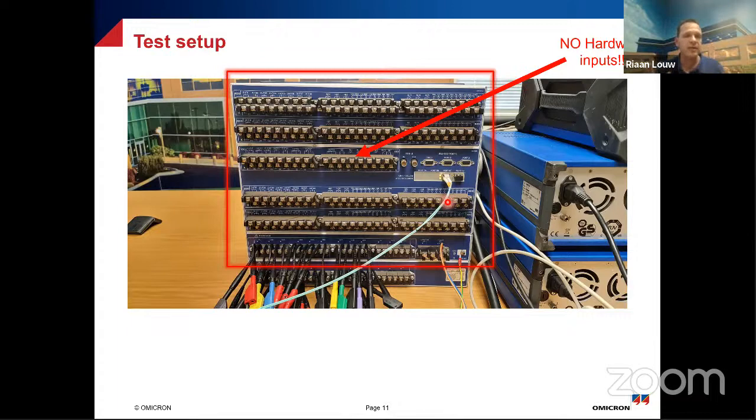I mean, considering testing an 18-bay busbar, if you have to wire in, and let's say, for example, it's a double bus with a transfer, then you have so much wiring that you would need to do to get all the breaker and isolated positions into this relay and simulate all of that if you want to do a full system functionality test.